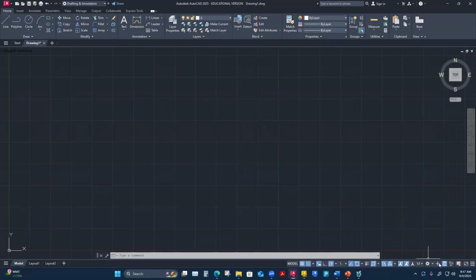And then what do I have? My annotation monitor, that's something I use on my drawing sometimes. I'll get to that later. Because I'm applying some automated scale going on in my drawings from model space to drawings, some things can get out of whack, and this little monitor is kind of like a little check system. It'll bring up an exclamation point when things are not jiving from model space to paper space or something. So I have it turned off right now.